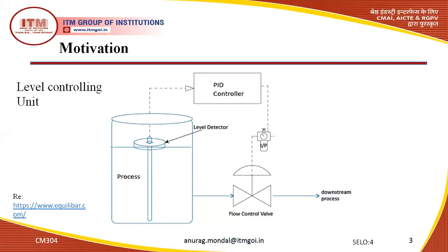For example, in this vessel I have a flammable liquid. So we never use a detector which uses electrical signals, because we know that whenever there is an electrical signal or electrical spark, the flammable things burn out. So we never proceed with a particular instrument or sensor that has some electrical or electronic component. We need to be careful about this.